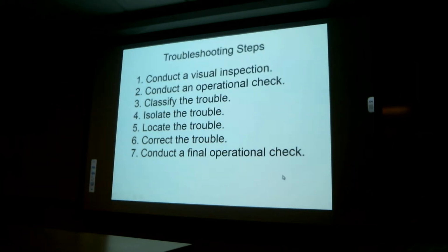You don't have the luxury that the manufacturer does of just swapping out parts to see if something will make a component or the system work. When you're working in the field by yourself, you're going to have to figure out what's wrong on your own. When I was at Sikorsky, there was a lot of shotgun troubleshooting, but they could afford to do that because they had multiple components they could take off a production rack and try to correct a problem that might develop as an aircraft is getting ready for delivery. But you as a mechanic don't have that luxury. You've got just what you have, and you have to be able to adequately isolate the problem